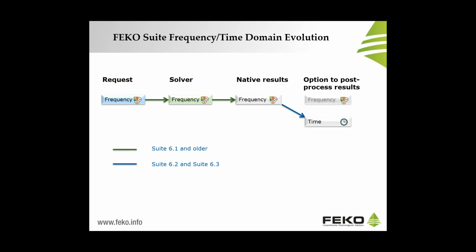Later, when we launched Suite 6.2 and also with Suite 6.3, the time domain analysis support was implemented in post-FEKO, replacing the old time FEKO component. Support for time domain modeling was included not using a time domain solver, as we are doing today with this new release, but with intelligent FFT and inverse fast Fourier transforms conversions that are hidden to the user.